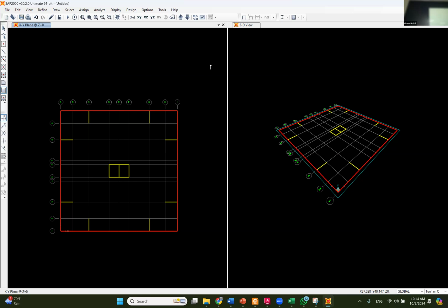Okay, so the first thing I need to put hinges, but to put hinges, I need to create joints, but to create joints, I need to divide this slab so a joint can be created here, or I have to draw them one by one. I'm gonna have a lot of them. Maybe it's gonna take, I don't know, 5-10 minutes. But once we draw this, the joints are gonna be created, so it's gonna be easy to put the hinges.